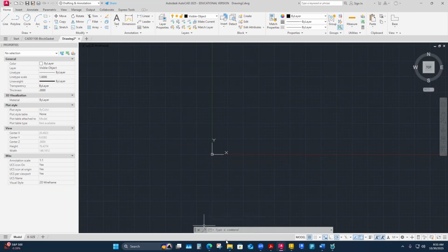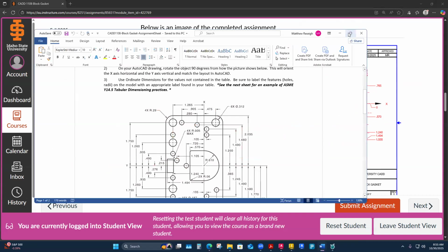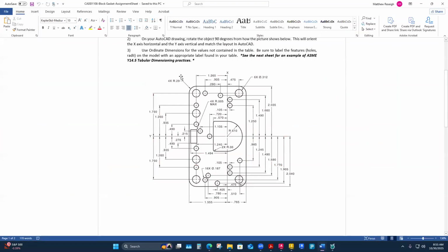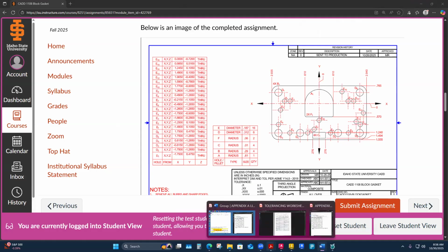The other thing to note here, as I think about if you've finished it up, our dimension style is just 2 decimal places. So we could probably create a third dimension style, would probably be the best. That's just because from the engineering sketch that I'm given, these are all held to 3 decimal places. So when I get to the dimensioning side of this, my 2 decimal place system isn't going to be sufficient to carry this data. I've got to kick it out to 3 decimals. I think every dimension I see in here is 3 decimal place. So for those of you that have worked ahead and maybe you're at that stage, maybe I'll create that real quick just because I know that I'm going to need it.